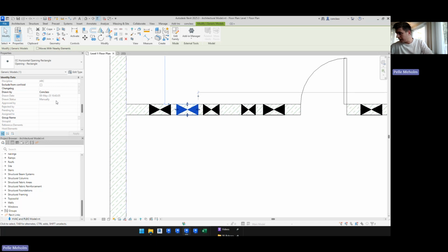How do you handle linking the HVAC IFC models to Revit? Since the files are too big, we found it hard to run with them. Well, that's probably an IFC issue. In case you receive an IFC file, we would recommend that one person in the project opens the IFC file. Revit will then create an RVT file of the IFC file, and this RVT file can then be linked into your main project. That would be a possibility.